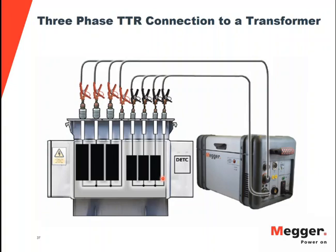Now, when you isolate your transformer, the normal procedure will be to open a circuit breaker, to open a vector switch, to open something to isolate your transformer, and do an offline test, which is your ratio test in this case. When that procedure is taken in place, you will have a little bit of a DC component going back to your transformer. So if you really want to start from zero the procedure of testing your transformer, avoiding any remnants of magnetization on it, you will demagnetize the transformer first, then you will do your AC testing, you will complete your procedure with the DC testing of winding resistance, you will demagnetize, and then you will energize the transformer again.